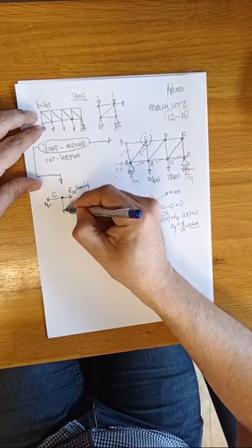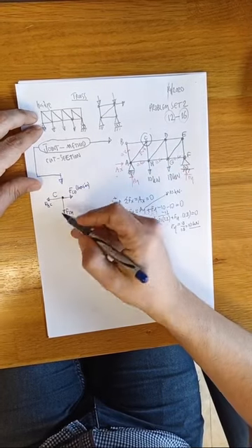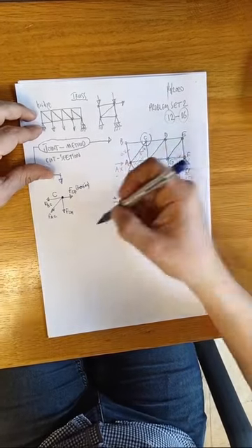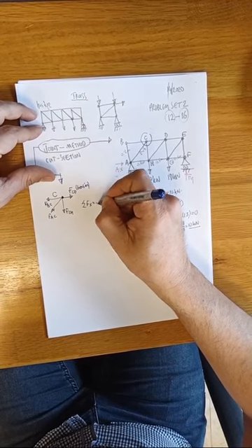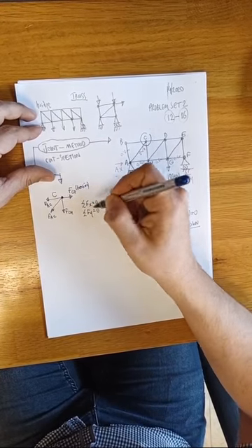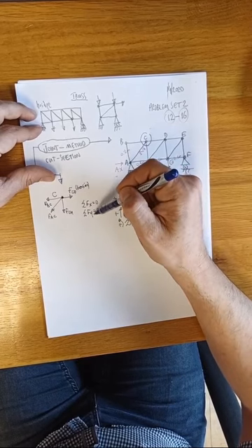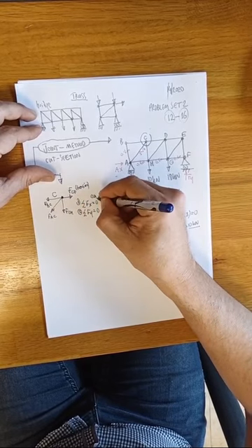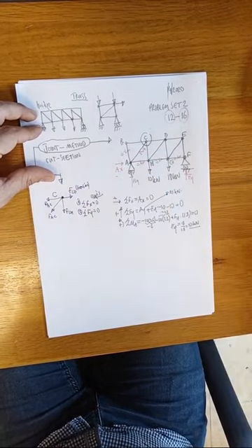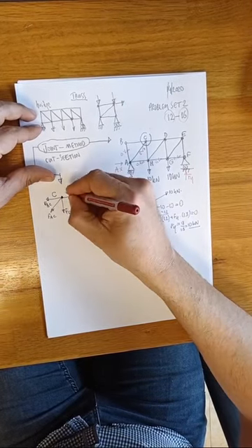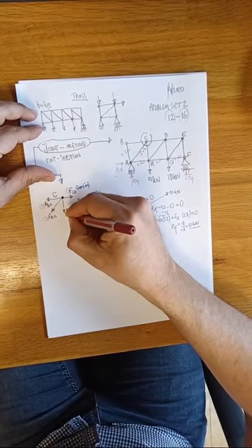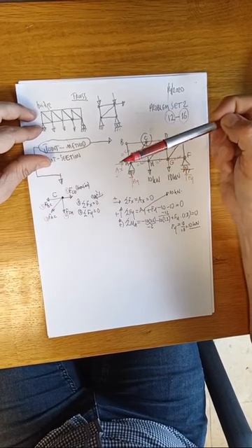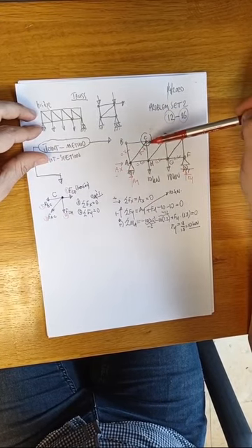I'm taking FCH also. I'm taking everything in tension, as you see, okay? And after, I will try to analyze this C point. But as you see, if you apply the equilibrium conditions like this, how many equilibrium conditions for a point? We have 2 equilibrium conditions. There are 2 equations, it means. This is one of the equations, this is another equation. These are equations, but how many unknowns? Don't you see? There are many unknowns here. This is 1, this is 2, this is 3, this is 4. You cannot solve, or you shouldn't start the solution or strategy from C point, okay?